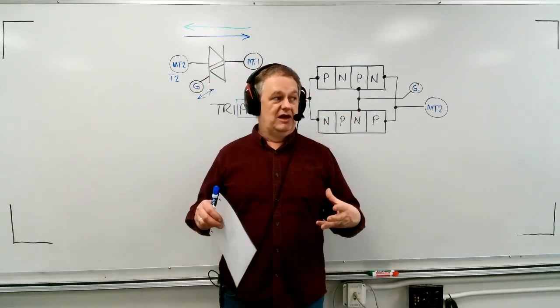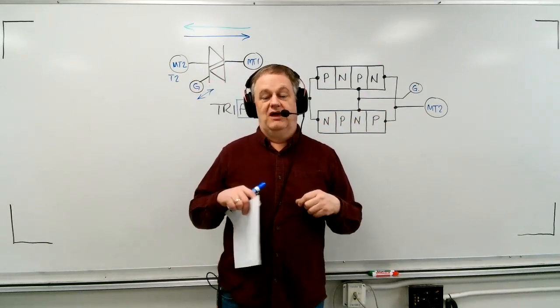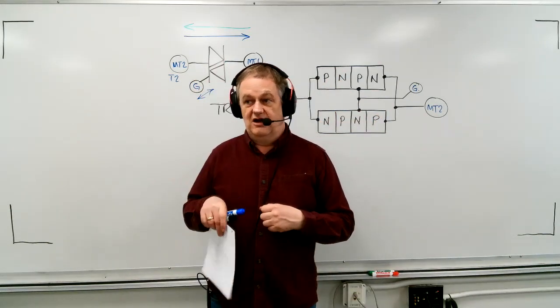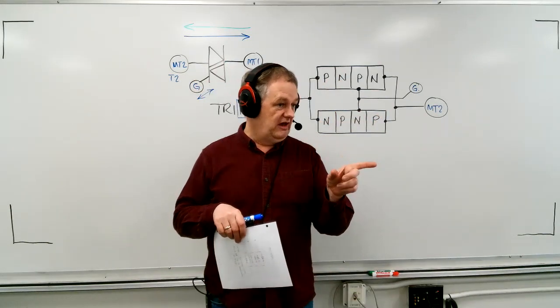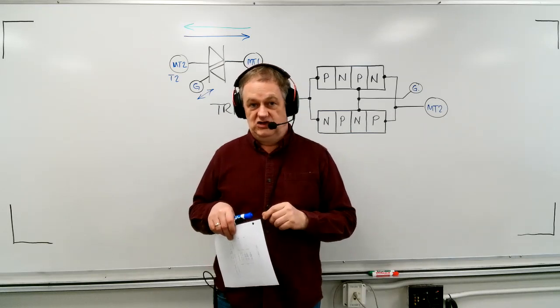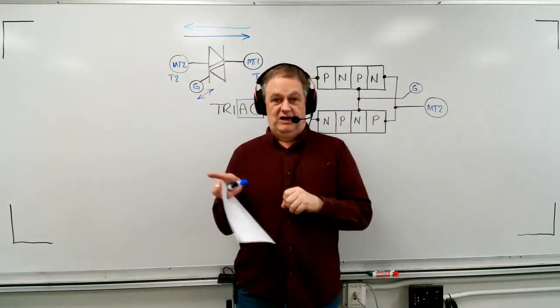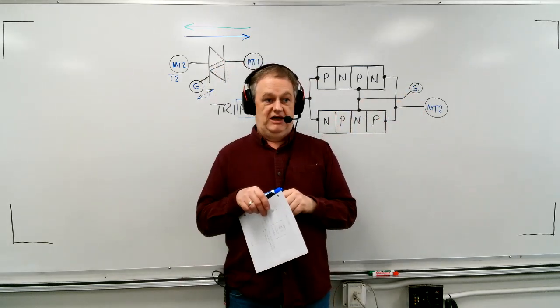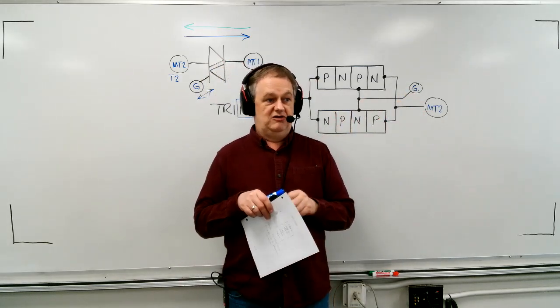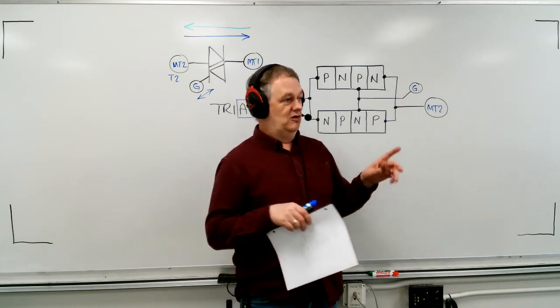And so you have to hook up a trigger circuit that will adequately fire one SCR in one alternation and then fire the other SCR in the second alternation. This one, the gate is hooked up so that it fires one SCR, and then in the next alternation, the same gate just fires the other SCR. So, it's AC.